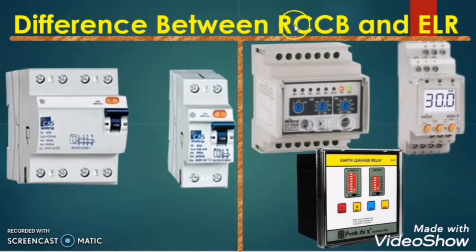The fun fact is that the RCCB and ELR have the same function, that is giving protection to humans and stray animals from the earth leakage fault current. And the second thing is that they have the same operation also, meaning the working principle of the RCCB and the working principle of the ELR are exactly the same. If the function and the operation are the same for RCCB and ELR, then what is the difference?